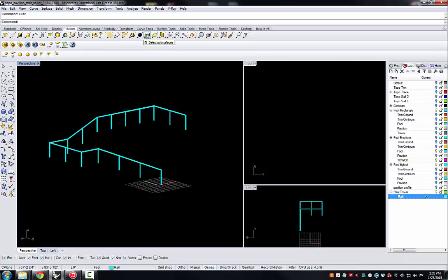And I'm going to select all polysurfaces, which are all of these pipes. And I'm going to join those together. And let's make sure that they are joined. They're not entirely. So instead, I'll select all of those polysurfaces and I'll group them, Control G. So at least we have them together as a grouped collection of polysurfaces that we can use in the future to apply materials and for rendering.